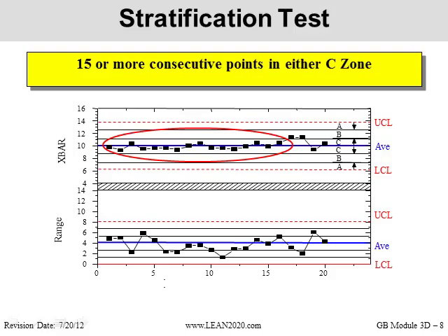So there are different reasons why we would see this. The bottom line is we're not going to understand why this happened by looking at a chart. All the chart is telling us is, okay, something not normal happened. Go back and look in your process to see if you can figure out what happened. So all these special causes are just going to cause us to go back and look at the process. We don't want to look at the process when it's acting normally. We want to go back and look for something not normal happening.